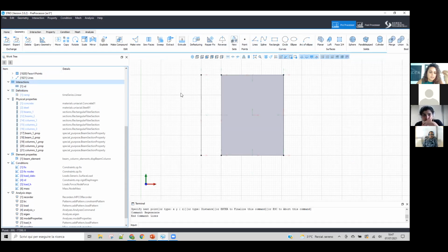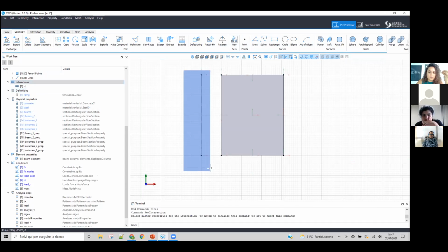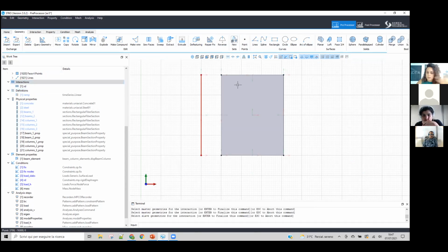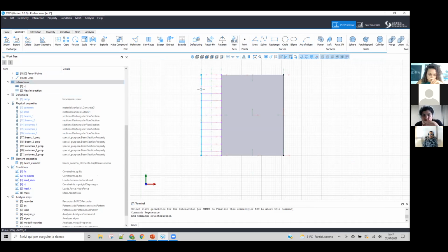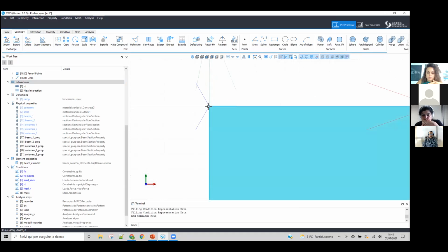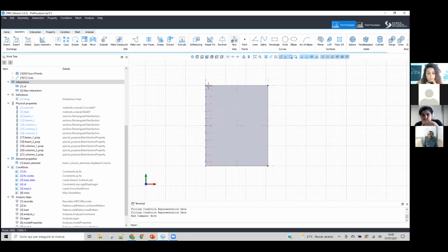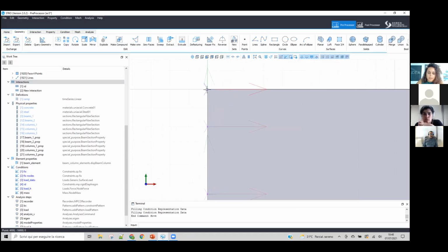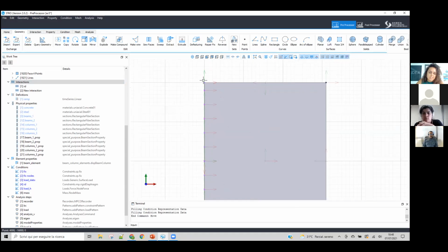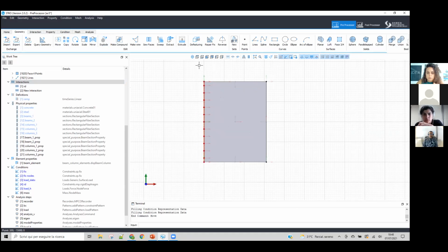And then I create an interaction between this and this. If I have, for example, a pillar that is close to a wall, then if I move this line back in, the interaction is collapsed in one point. So the location of the constraint and the retained node are the same. In this case, the equalDOF and the rigidLink will give you the same thing because there's no beam element, no line in between the two nodes. So it means there will be no relative rotation.